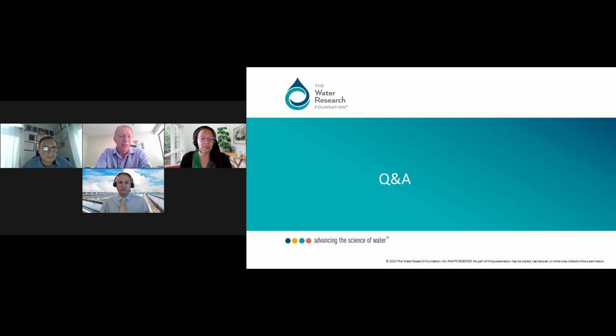Okay, thank you. We had another question come in. This one asks, would one of the speakers have any thoughts on pros or cons of placing analyzers, especially ammonia analyzers, in treatment structures preceding biological basins? For example, in the headworks or primary clarifiers, would that have any benefits in terms of the response time?